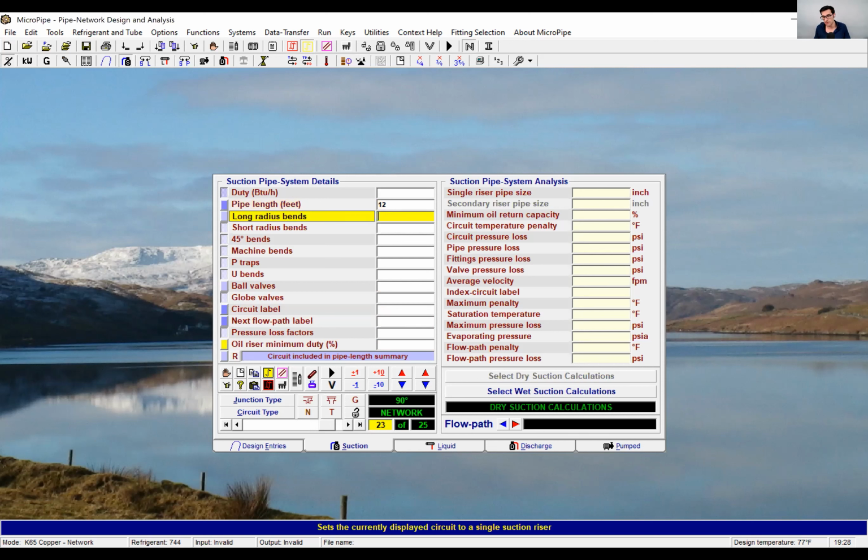Will you do this every time? No, you definitely would not. But when you run into those situations where there is a difficult problem, you can verify what that line sizing could be. Could you do it on a chart? For sure. You definitely could do it as well. We are calculating for a branch piping or a home run piping. This would be a home run piping system that James is doing, I believe.